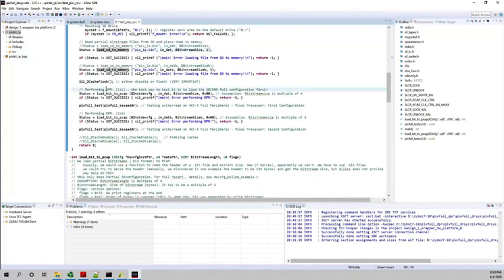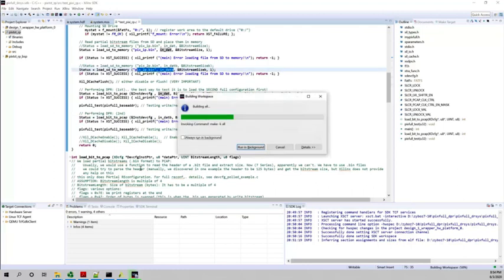And here, of course, when you are ready to perform DPR, partial reconfiguration, all you have to do is use this command, load bitstream to pickup, with a pointer to whatever bitstream you want to load. So here we're loading first the first variation, and then we test again, and then we load the second variation and test again, and that's all. That is all that you actually need to do.